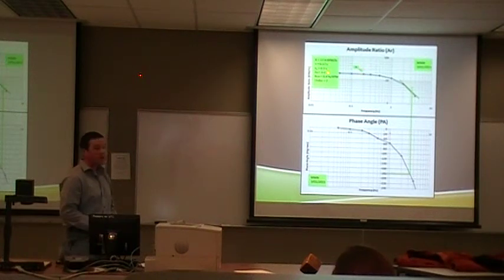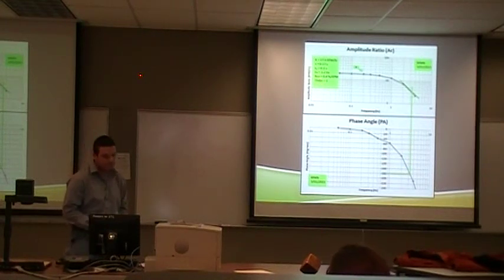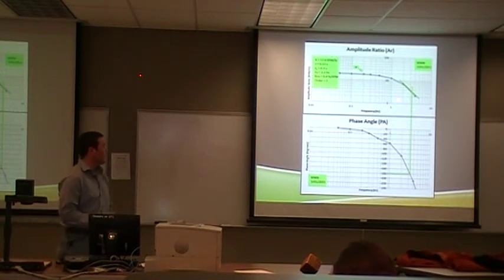T0 comes from the phase angle equation, and we use it at the ultimate frequency, which we found at minus 180 degrees, and the corresponding frequency was about 3.2 hertz. Also from this, we come up to the amplitude ratio, and 1 over this gives us the ultimate controller gain of about 0.4% per RPM. The negative of the slope at the higher frequencies of the amplitude ratio gives us the order of our system, and for this it was about 2.